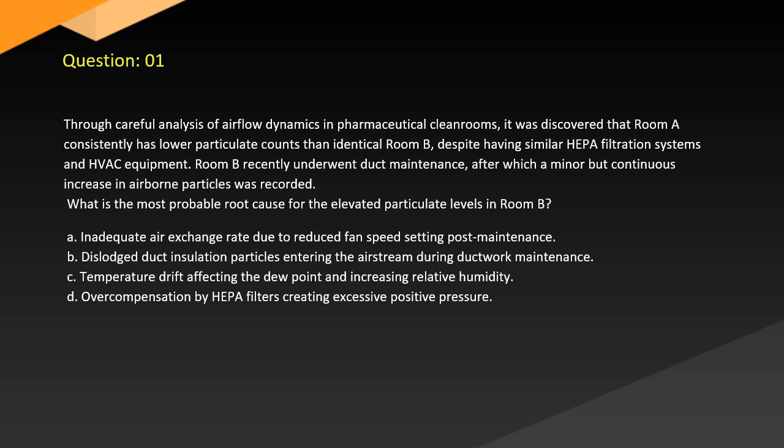A. Inadequate air exchange rate due to reduced fan speed setting post-maintenance. B. Dislodged duct insulation particles entering the airstream during ductwork maintenance. C. Temperature drift affecting the dew point and increasing relative humidity. D. Overcompensation by HEPA filters creating excessive positive pressure.